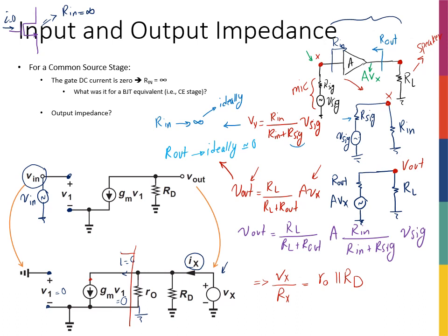Of course, we're going to solve more examples, and we're going to see that this is the simplest possible amplifier. This is for the case that I have just an amplifier like this. So V in is connected to here, source is connected to ground, drain is connected to some RD to VDD. But definitely, if things get more complicated, we're going to have a more complicated kind of input and output resistance. We're going to talk about it in future slides.